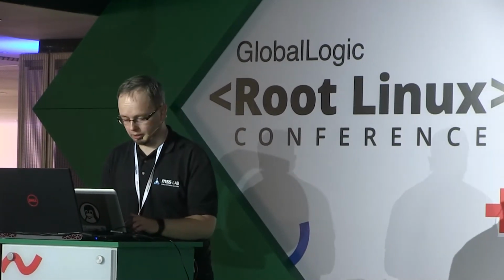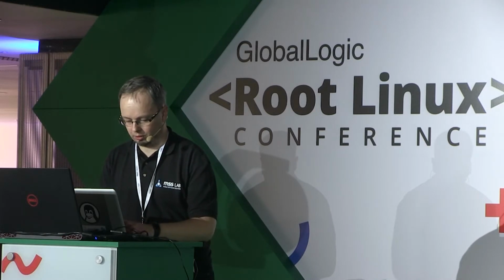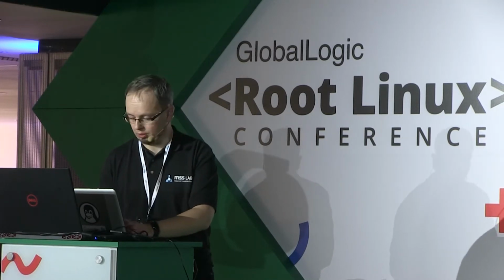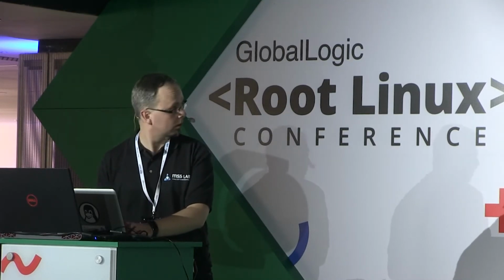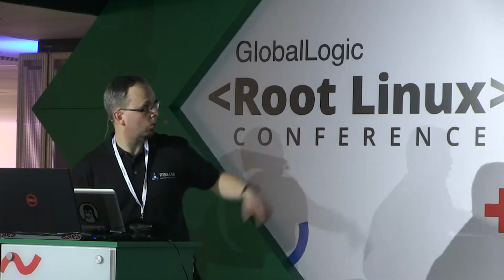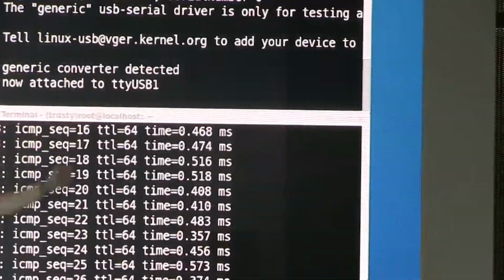So now we tell the generic serial driver at the host side about this new device, so I must gain root power. Okay, so echo ABCD 1, 2, 3, 4 to sys bus USB serial drivers generic new ID. Watch the host diagnostic messages. A new ttyUSB1 device has been created.